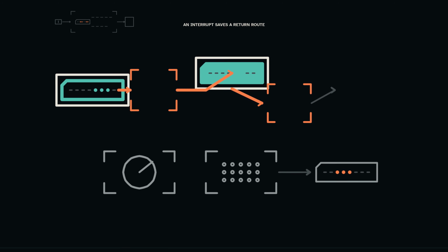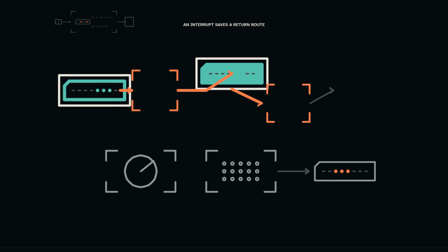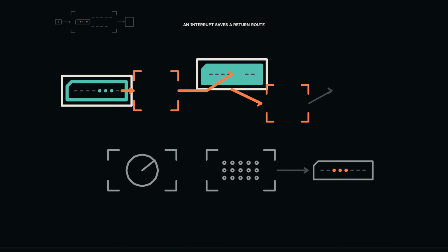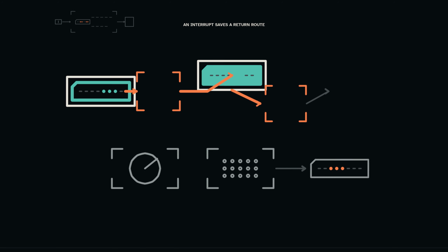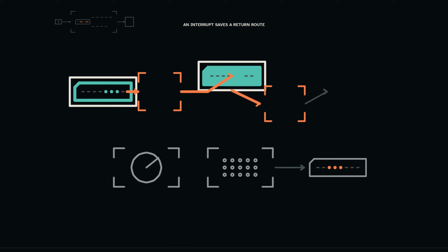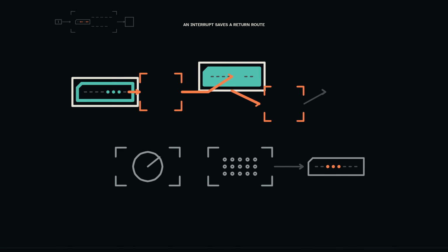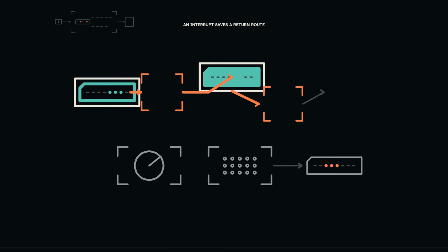If the return address were not saved, returning would be a guess. If the handler changed registers without saving those required by its calling rule, the interrupted program could resume with corrupted values. Interruption works because preservation and return are specified, not because control magically comes back.